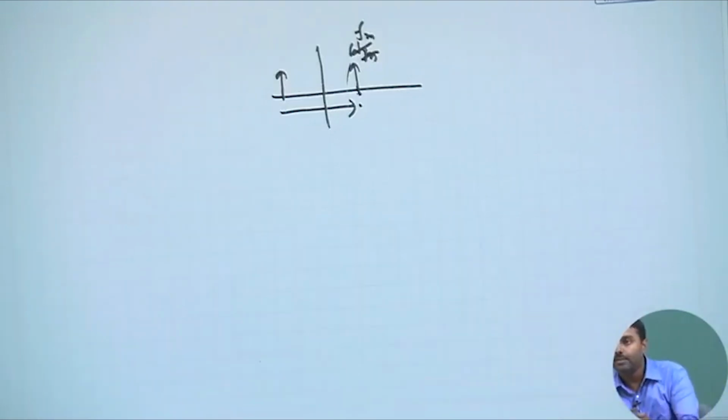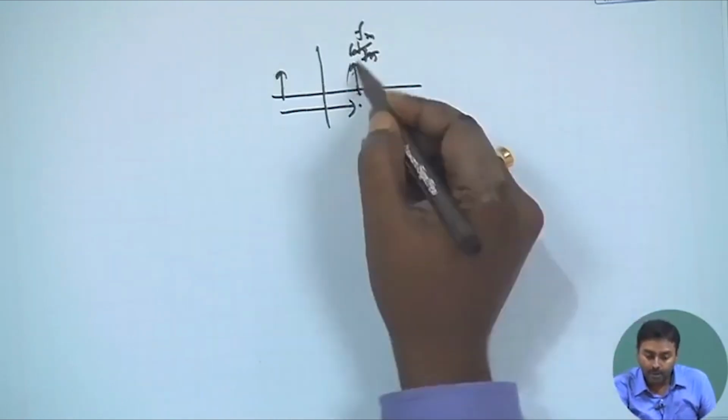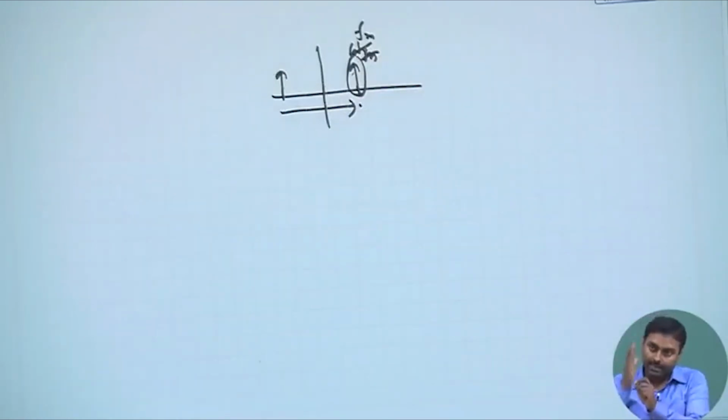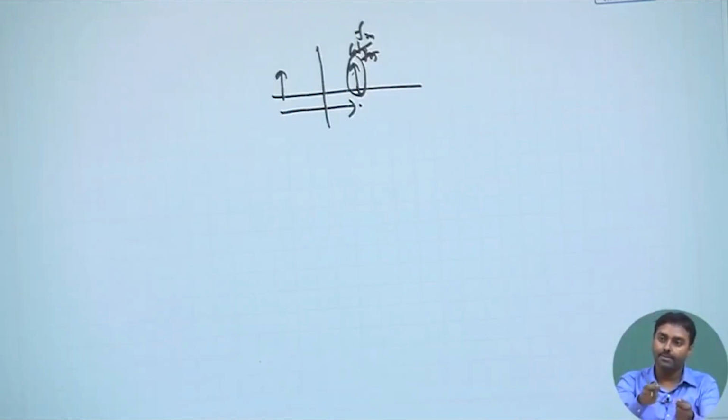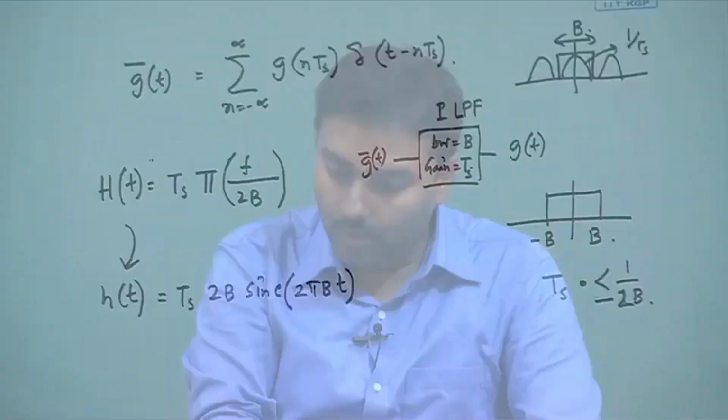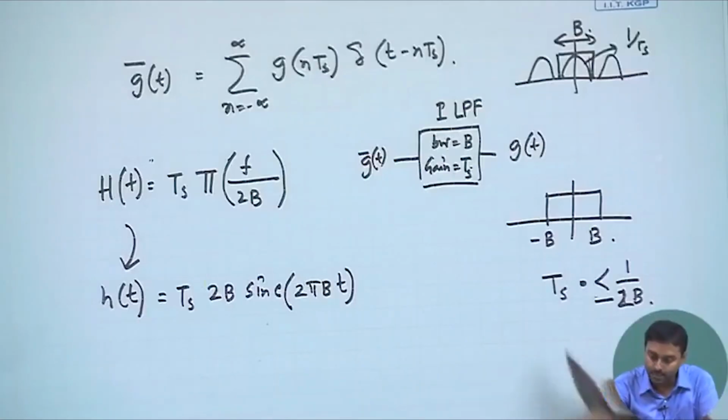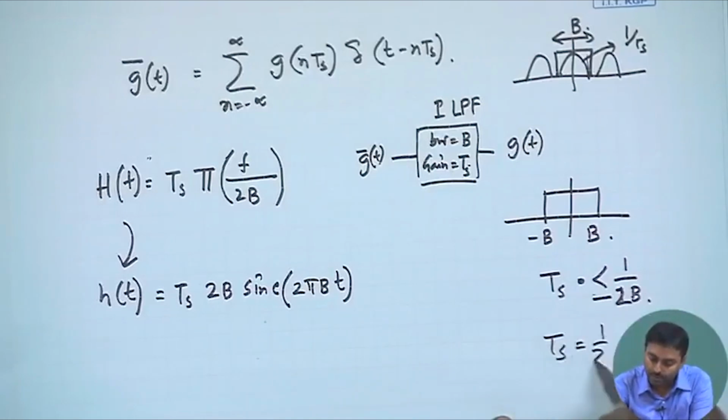There if we start doing sampling, probably there will be superimposition of things. Okay. So, as long as there is no sample at the end of the band, we can always even do Nyquist sampling at that frequency. Okay. So, basically instead of writing this less than, I can also write less than or equal to, and the best I can do is Ts equal to 1 by 2b.